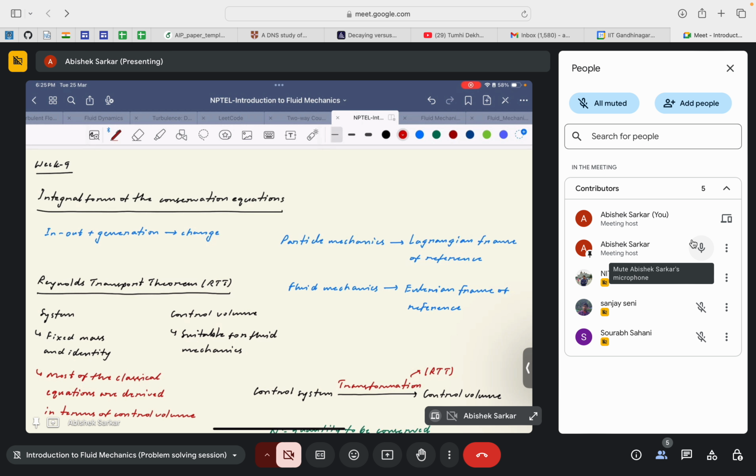So any conservation equation that we initially discussed is based on this simple fundamental principle: if we consider a particular control volume here, then the net rate of change of a certain property within that control volume is just the net influx, from which we subtract the net outflux, and then take into consideration the net generation of the property within the control volume. So this summation of in minus out plus the generation will give us the net rate of change of that particular property within the control volume. And that property might be anything such as force, pressure, or even the velocities.